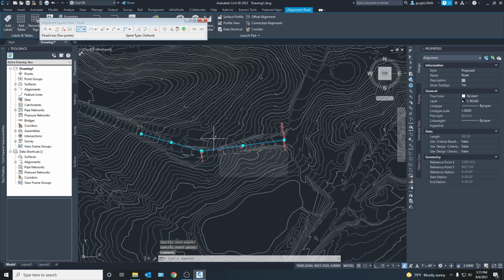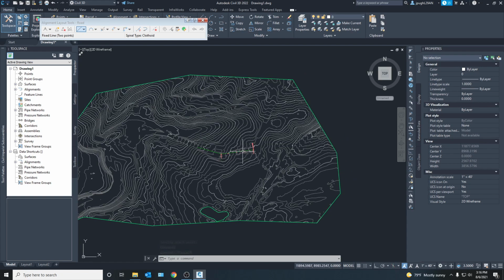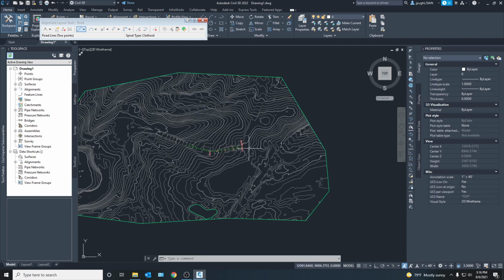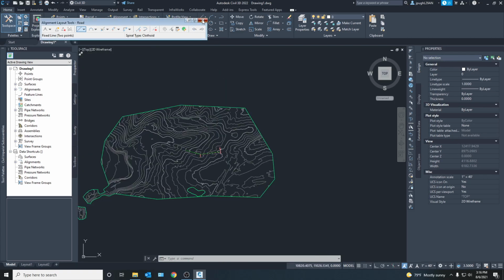and it looks good. So now that you have your alignment, there's not much there. There are no elevations. You could create a corridor off this, but it's just going to follow the alignment and have no profile. So it's just going to be straight on the ground, and the alignment will always stay down.